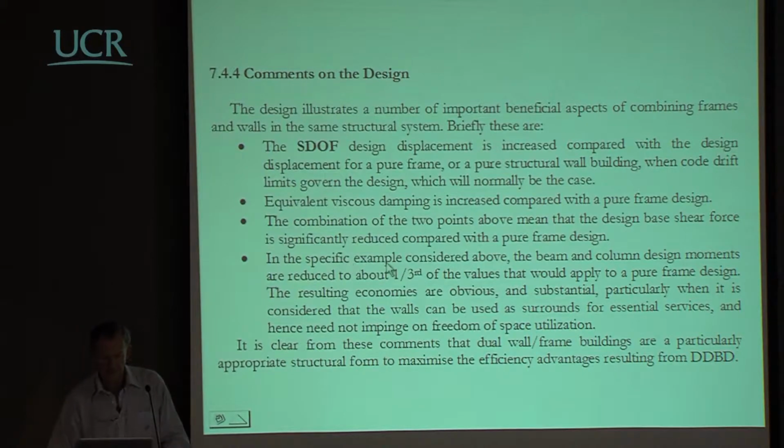In the specific design example considered, the beam and column design moments are reduced to about 1/3 of the value that would apply to a pure frame design. And perhaps to discuss briefly the design aspects here, we have chosen, of course, to say that this is a dual wall frame system.